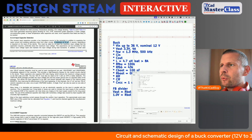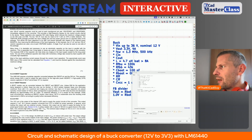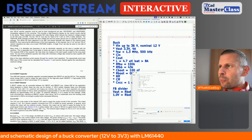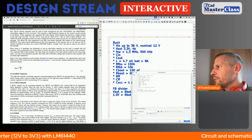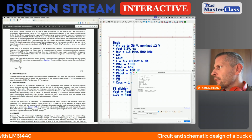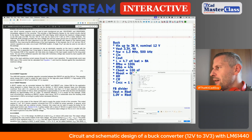I think we will use 2 capacitors of 22 microfarads, the same value as on the output, to have the design lean. So input will be 2 times 22 microfarads, 35 volt plus.